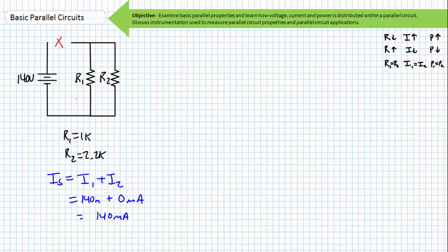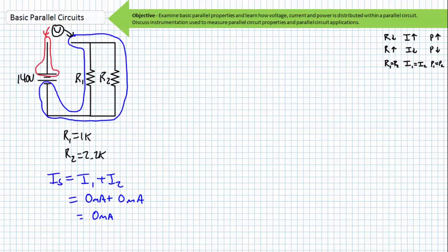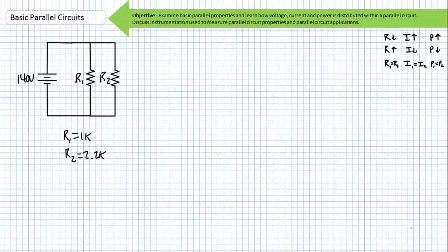Current through the whole circuit ceases since there is no complete path from our source through our parallel combination. No current will flow through either element and no voltage drop will occur across either element. The voltage drop will occur across the open. Obviously, with no current drawn by any element, the source will provide no current. Let us now consider the influence of shorts inside parallel relationships.